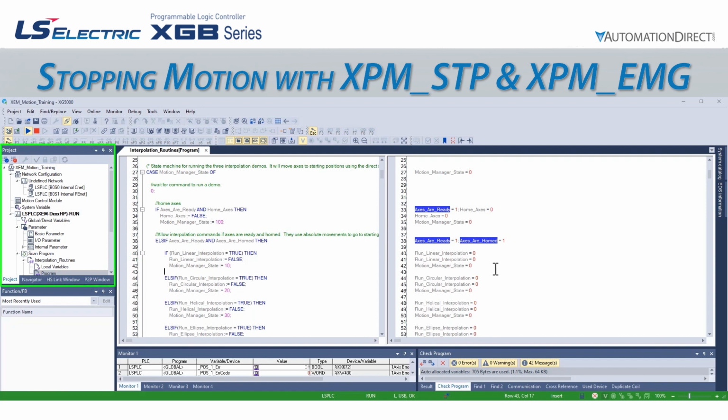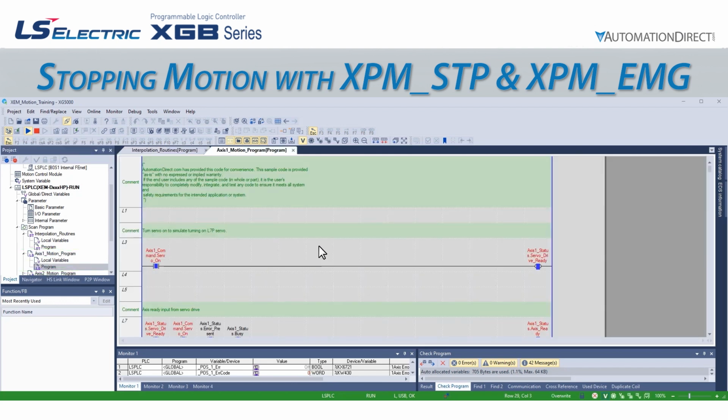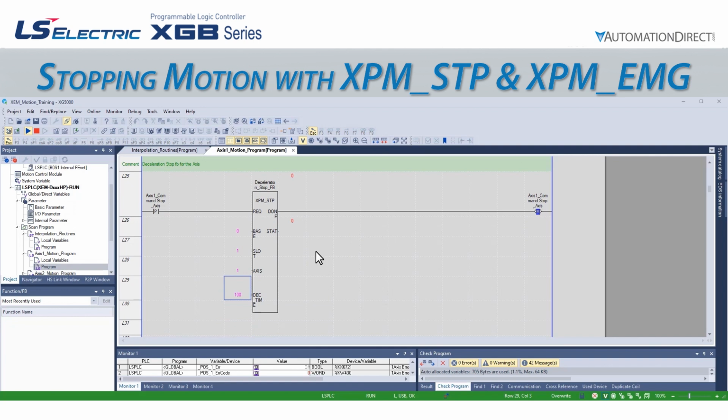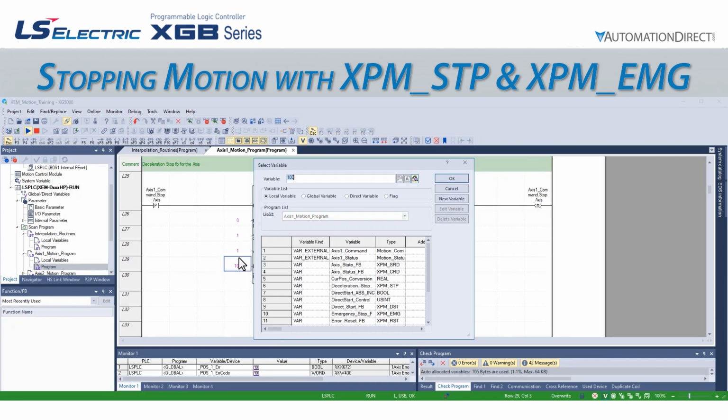If we go to the project browser on the left side of the screen, maximize Axis 1 Motion Program, and double-click on Program, it will open the program in the main programming window. Our decelerating stop command is on line 25 of the code. We see that it has a decel time of 100 milliseconds. Let's change this to 5 seconds so that we will have time to see the deceleration in the trend. Because this value is a constant, not a variable, we must leave monitor mode to change it.